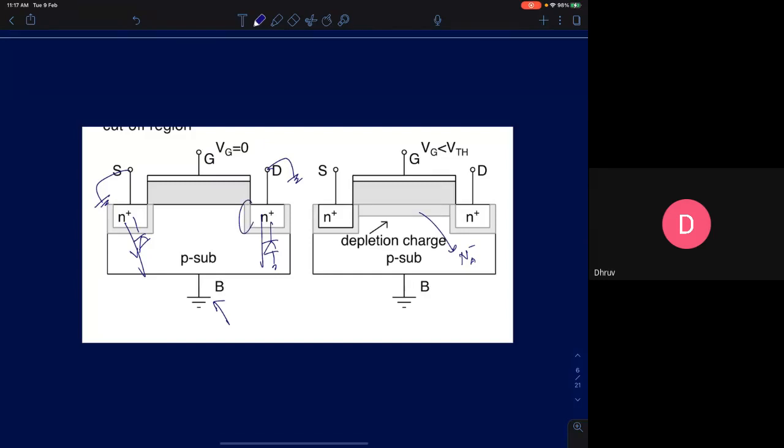So you will have some space charge region or depletion region. The moment you have a PN junction, around the metallurgical junction between the P-type and N-type semiconductors, you will have a built-in region or a space charge region. This will be the region of immobile charge carriers. So that's the structure I've shown here.